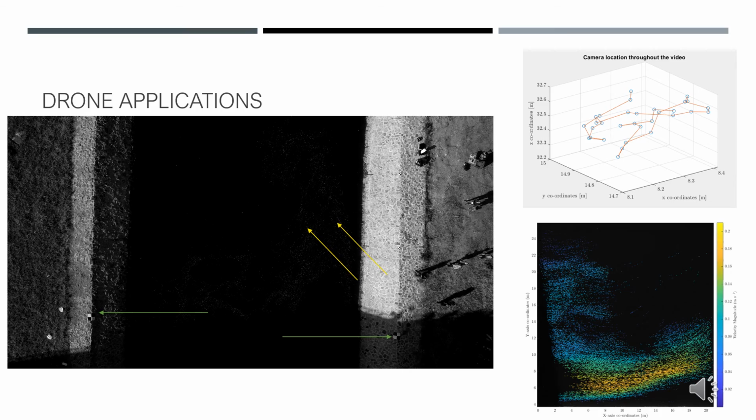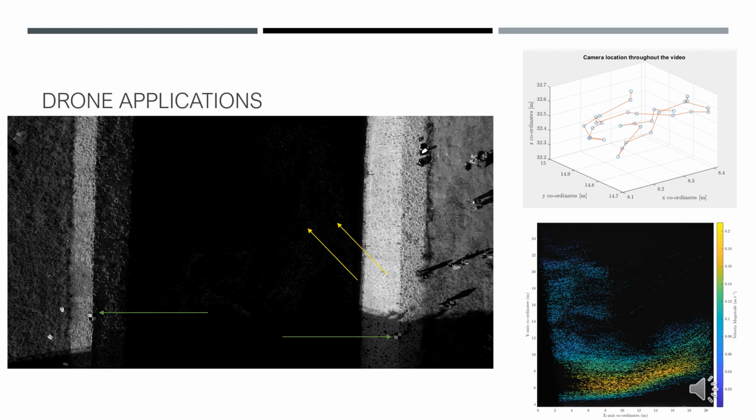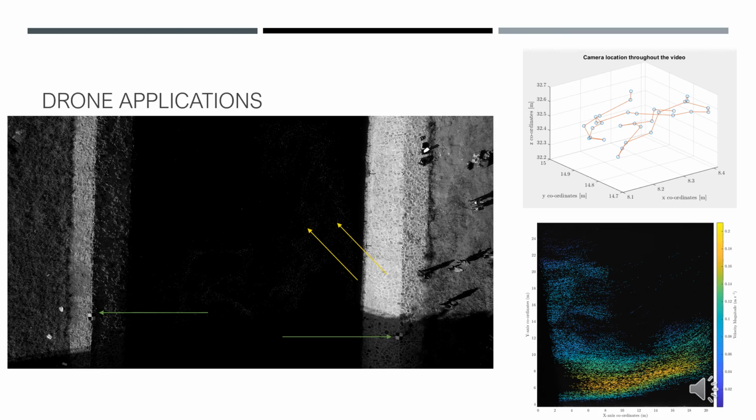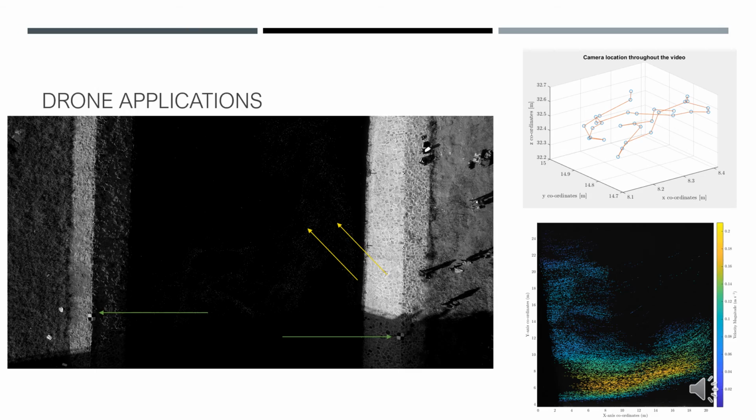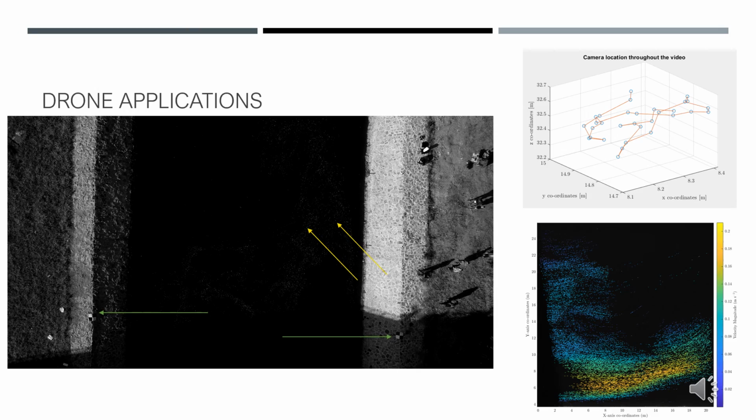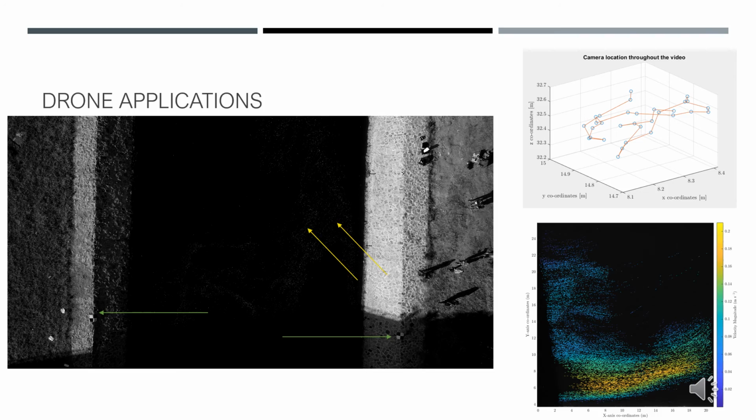The two arrows that are on the edge of the river are highlighting some GCPs, or ground control points, that were placed to help stabilize the image. The two arrows that are placed in the stream show where the traces are floating if you're struggling to see them. The results we get from this video are shown in the bottom right.